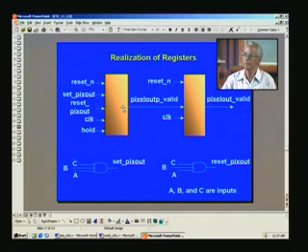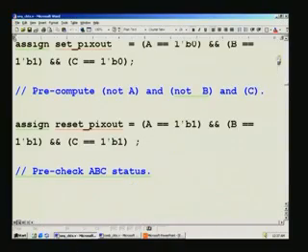So, in other words we want to delay one particular signal, in this case what is called pixel out valid, with a P standing for the previous value. Actually this is the real value that we are interested in, but we want it at the next clock pulse. So, what we do is we put another register and register it there, that is what you have here. We have already seen this before, and whatever set and reset conditions are all applied here, and the corresponding code is what is shown here.